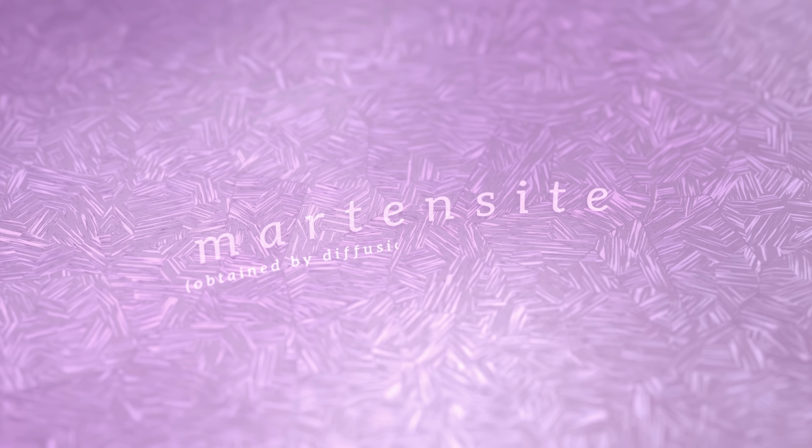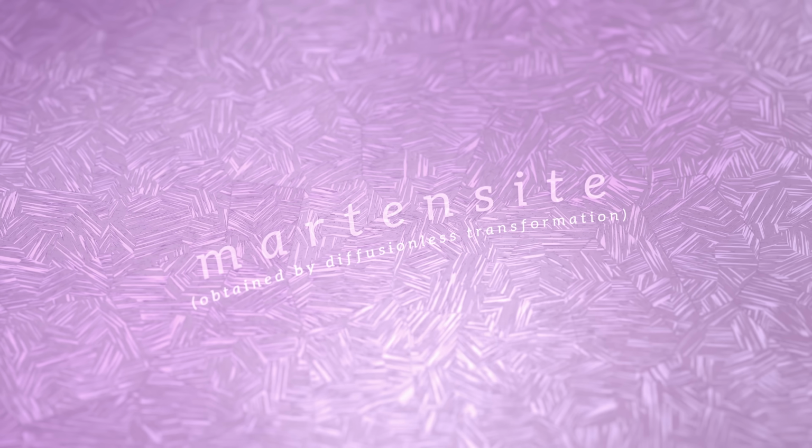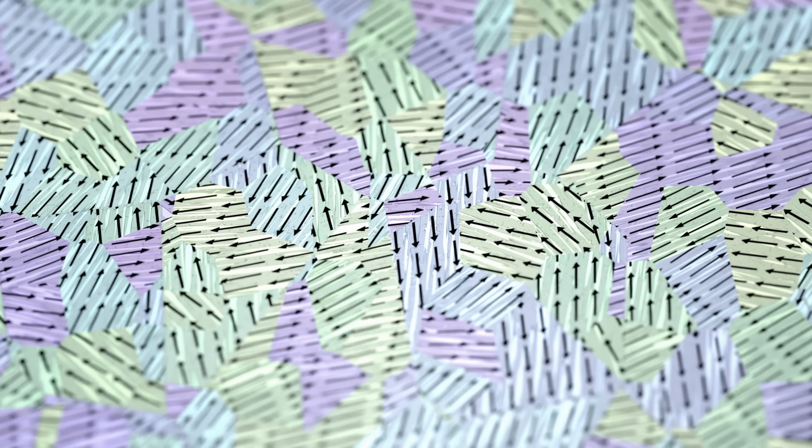This happens so fast because the transformation from FCC to BCT is diffusionless. Unlike the other phase transformations we've seen, it happens without any long-range motion of the atoms. The result is a microstructure of long, thin plates of martensite slicing through the prior austenite grains, each plate being a region where the atoms have all displaced in the same direction to form the BCT lattice.